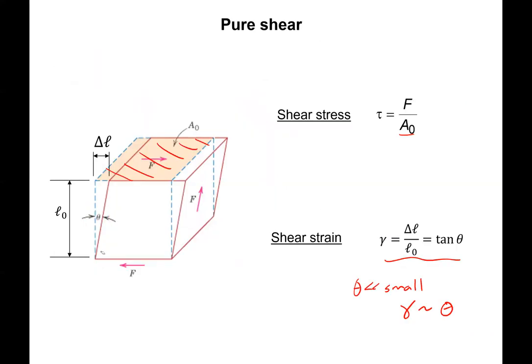Shear stress and shear strain are defined as the distortion in the sample. So if we have a cubic block, say for example, and we were to apply a shear stress to the surface, this is kind of like having a deck of cards and pulling on the bottom of the deck and pushing on the top of the deck. You create a shear, and it distorts the shape of the original deck. And so we would define that distortion, that delta L for the change in length, as defined in this figure over the original length, as our shear strain. Okay? That's also the tangent of the angle of distortion.